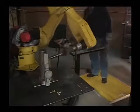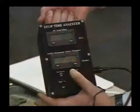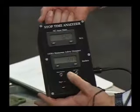Whichever way pressure-sensitive mats are used, they must be located where they will prevent workers from putting themselves in danger. And as with light curtains and pressure-sensitive trips, if there is any doubt about whether the machine is shutting down quickly enough, the machine and mats must be checked by a qualified technician.